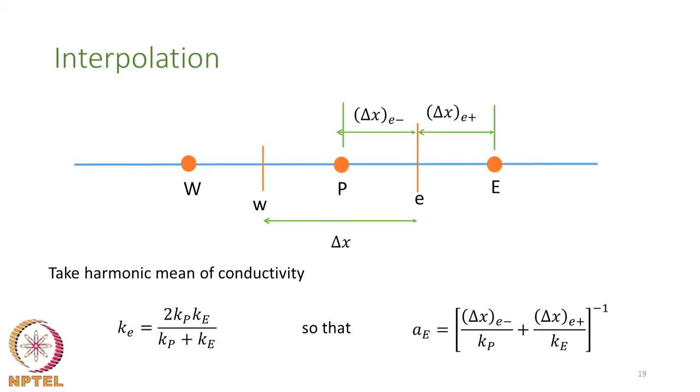The interpolation scheme is expanded here a bit more, and it is not as if we can take every parameter in the domain and then make a linear interpolation. For example, take the thermal conductivity. We have the choice of using interpolations using either linear or harmonic, and here the argument is as follows. Let us say that the control volume to the left of P has a thermal conductivity which is very poor compared to the control volume on the right hand side.